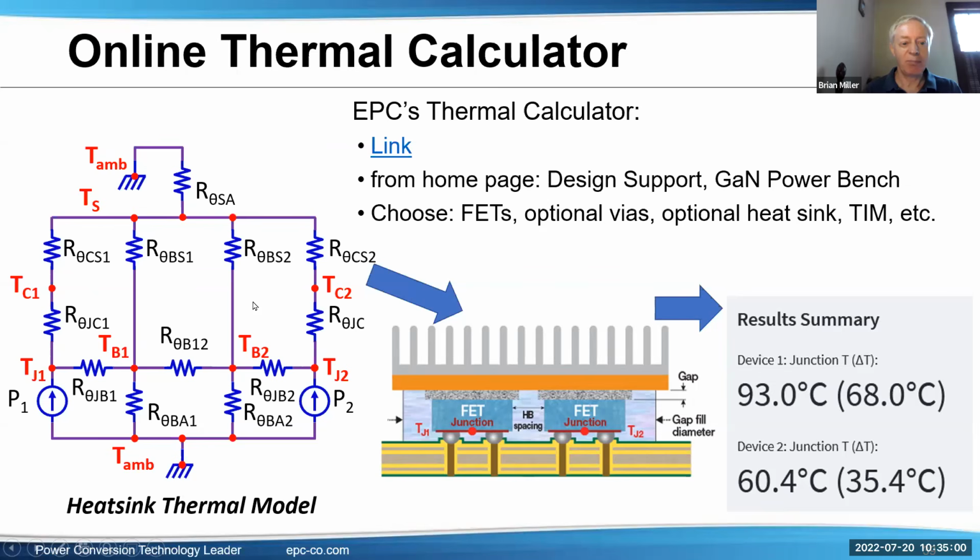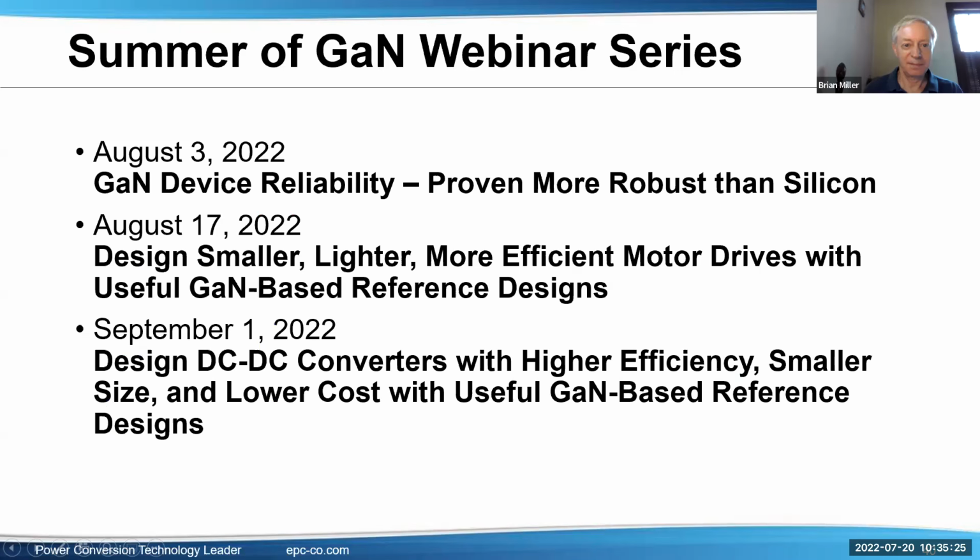But you can see for yourself as you go through that how things are working there. So in other words, you can skip the model, go directly to putting the circuit as you'd like it mechanically and thermally. And then there's a box with the result summary: under the conditions stated, in this case, 25 degrees C, what's the temperature rise and what's the junction temperature of the FETs? And I think that's it.